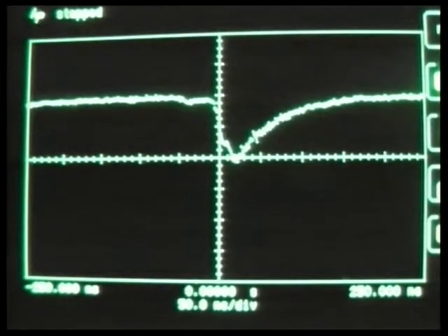So I was wondering if you could do it just with a cap from an I/O pin on the msp430 going into the rail, just have a falling edge on the other side of the cap. You can. In this case, I used the muxes so that I could switch to a particular voltage. So I can add a capacitor to a test point on my board, get the capacitor at the value that I want to glitch with, and then flip everything over.